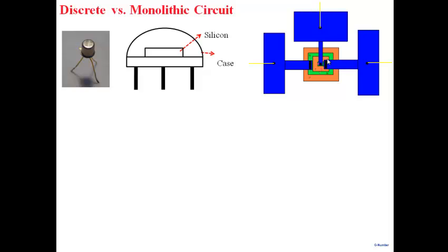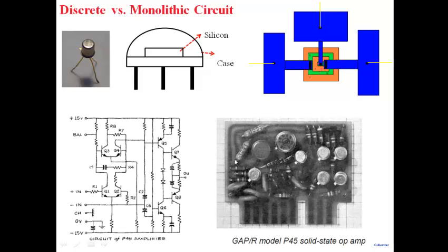And how do you make it big? Well, you make it big by attaching all these pads. Every transistor, every IC is surrounded by metal pads. You can see here, this is a big metal pad, nothing but a big piece of metal. To these pieces of metal, you attach very fine wires, and these wires are then attached to the pins. So even though the transistor is very small, in microns, you have to make it the size of a centimeter. Why? Because of my way of manufacturing. The way I manufacture is by holding it and putting it on a substrate. So the transistor is very small, but I have to package it into a large entity, which is 1 centimeter. And then, of course, one has to place it on a board and interconnect it with other transistors that you see here, and resistors and all that.